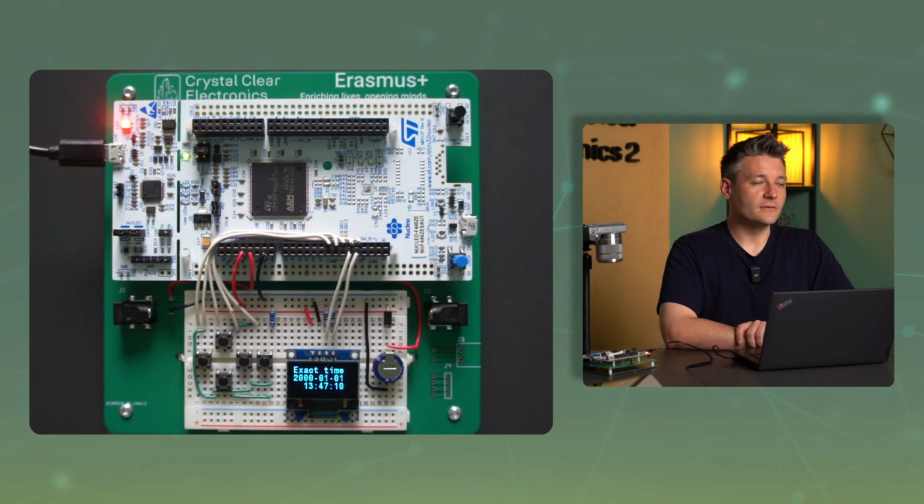The VBAT leg of the microcontroller is routed to leg 33 on the CN11 connector on the panel. This can be read from table 21 in the board's user manual. On our panel, this connector is not placed, so we solder this red wire here to connect the capacitor.